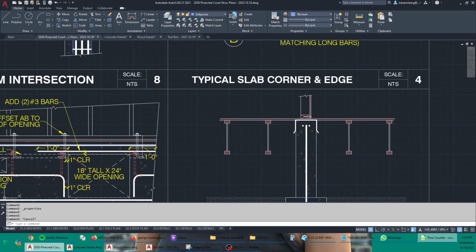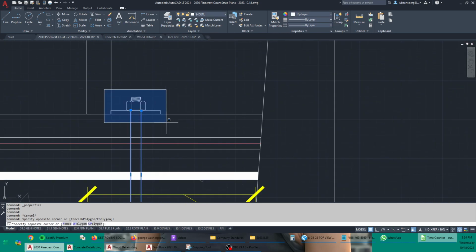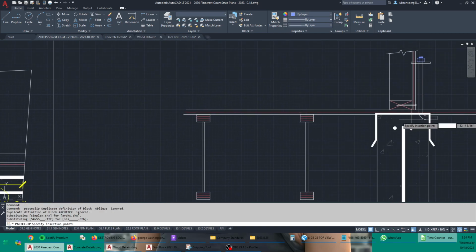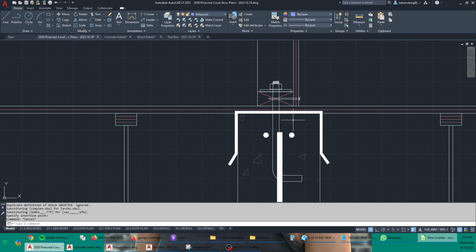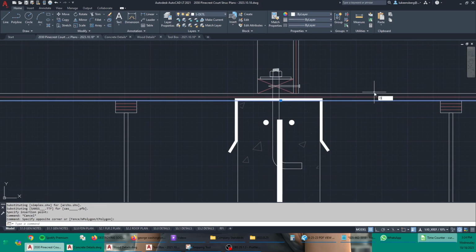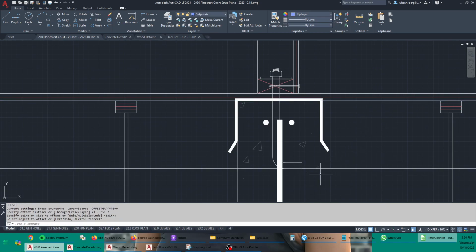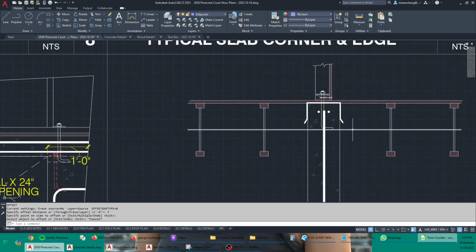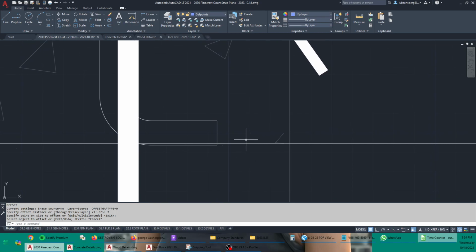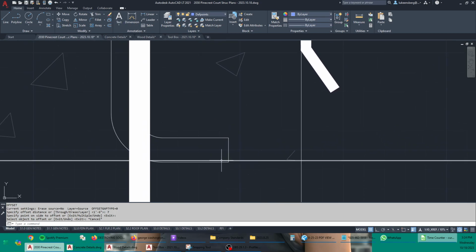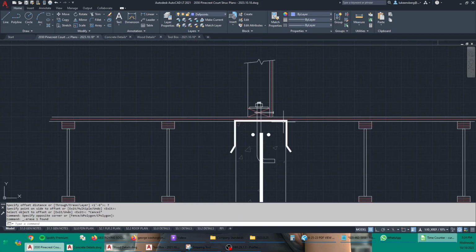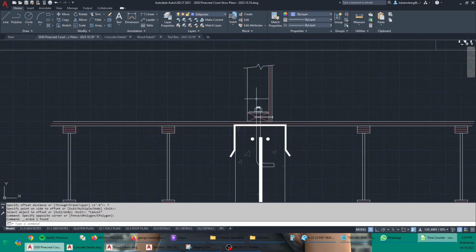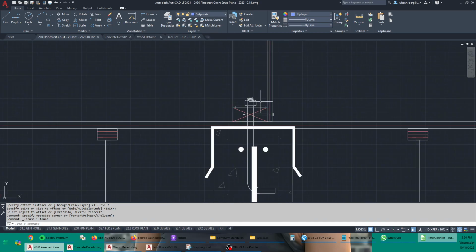Okay, I also need to grab some sill plate anchor bolts like this, put that into the wall. Boom, right there, centered in the sill plate. Let's check that I've drawn at least 7 inches of embedment. Yes, I offset that line just now by 7 inches, and I can see it's roughly to the bottom of the sill plate bolt. All right, so we've got our wall anchorage there.